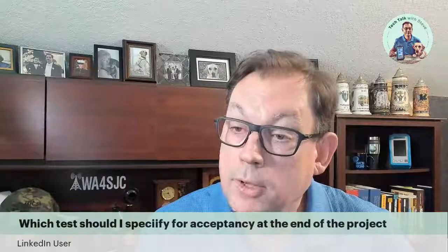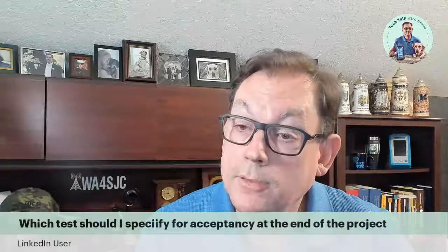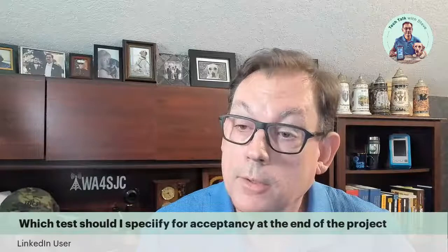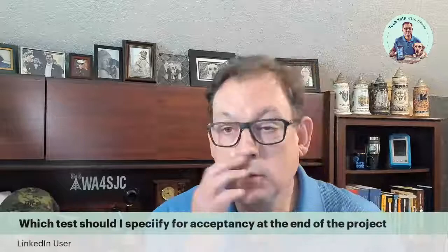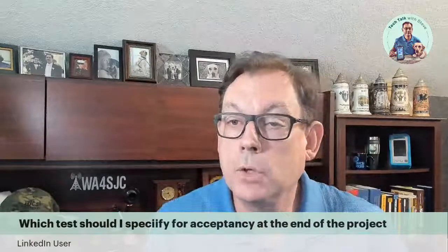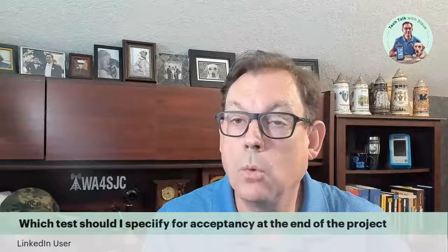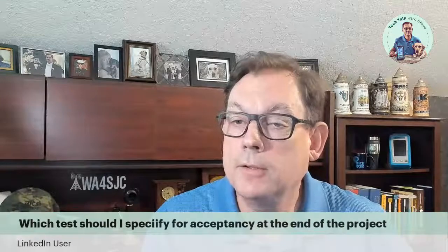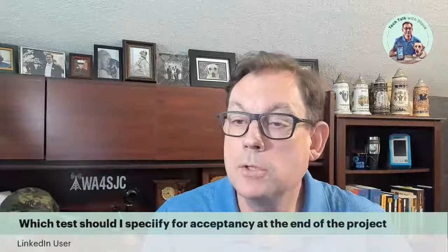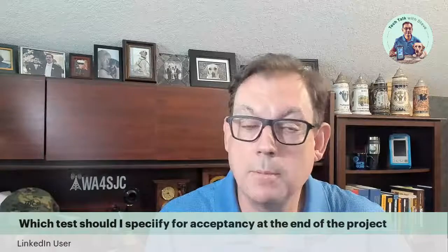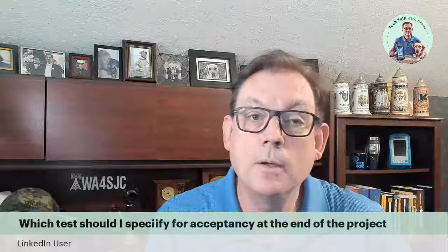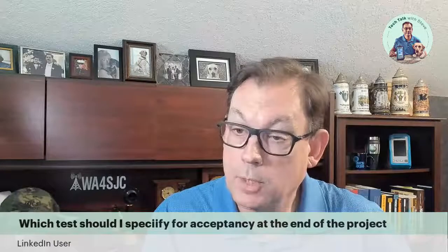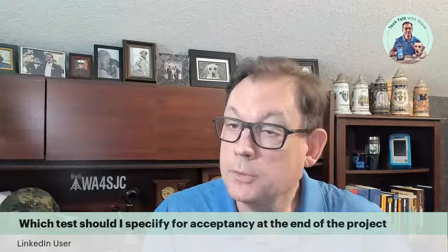So what test should I specify for acceptance at the end of the project? That's going to depend on your scope of work. What are you installing? The 568-D.3 that I was using is the recommended one. Of course, it's going to depend on the type of fiber. You're going to need to set that up as well. Whether it's inside plant or outside plant will change the limits per kilometer. So you'll need to be aware of those as well.